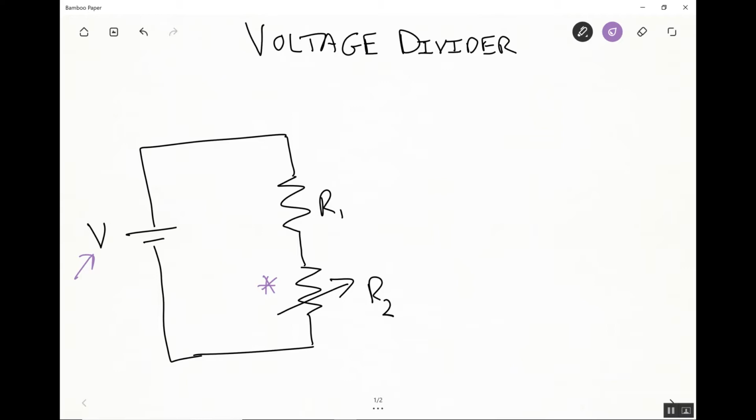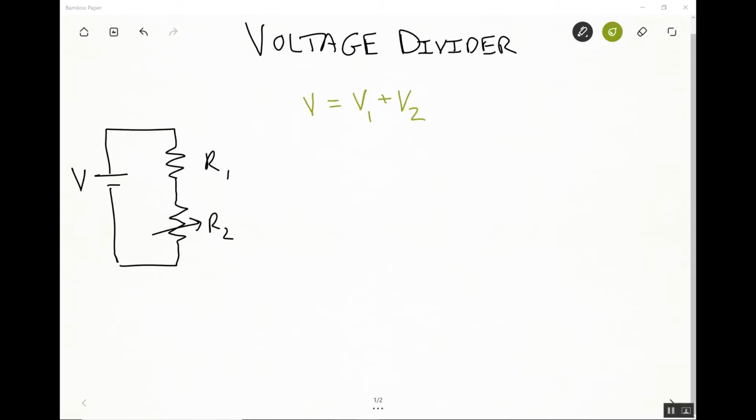Okay, so this is something I expect you to be able to do. If I give you a data sheet for an LED, or the voltage requirements and current requirements for an LED, I expect you to be able to calculate how big a resistor you would need to put in series with that LED to limit the current flowing through that resistor so it works without burning out.